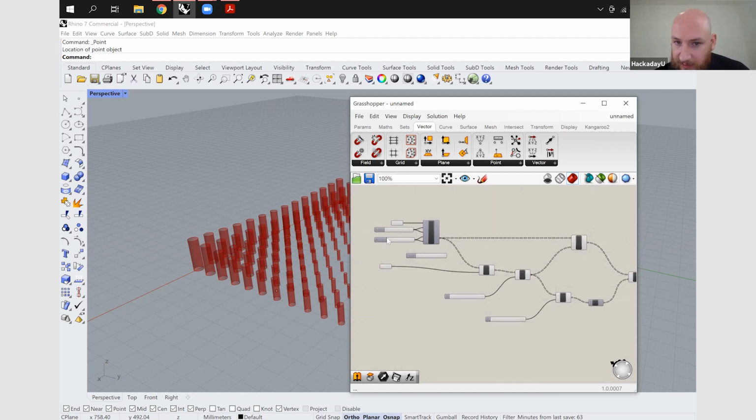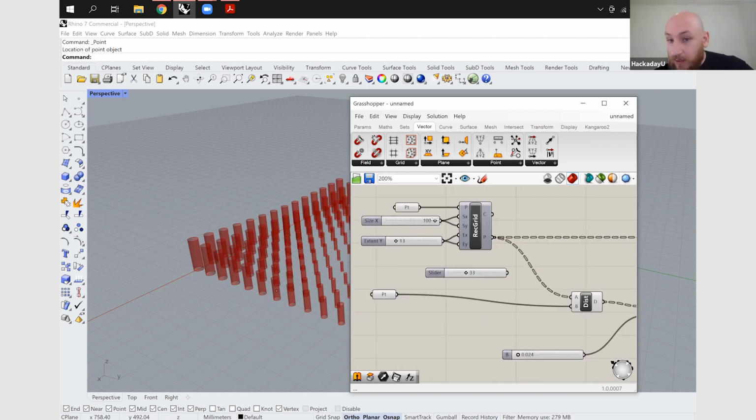Then we're creating sliders. You can create 4 sliders if you want. I just created 2, but you want to set the sliders to integers, not floating points, and set the limits to 1 to 100. And then left click to drag the slider into S of X and S of Y, and into E of X and E of Y.